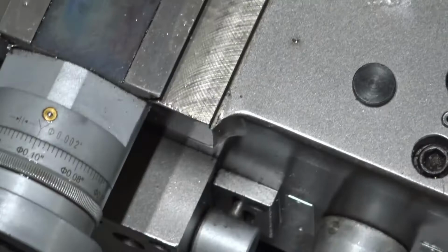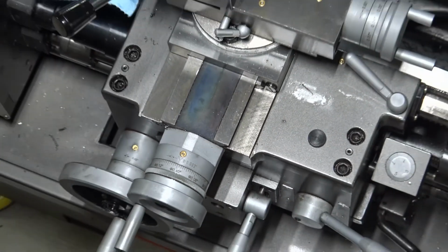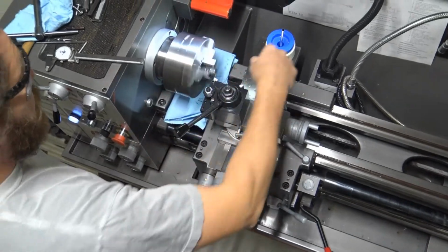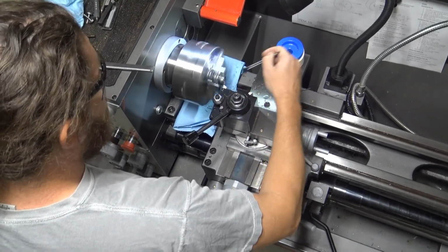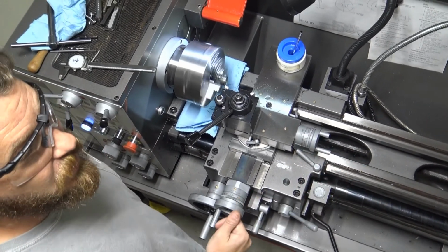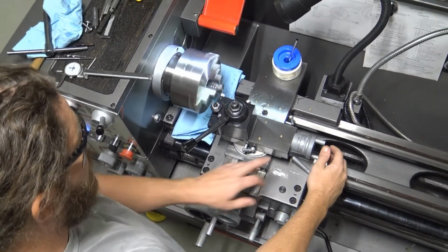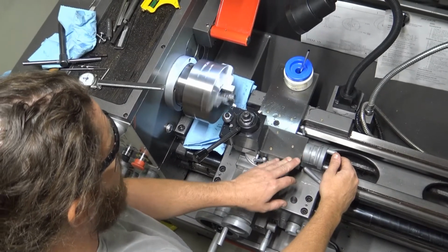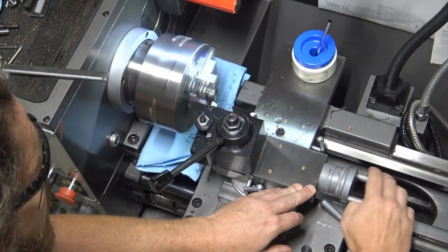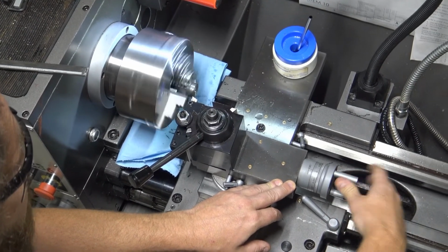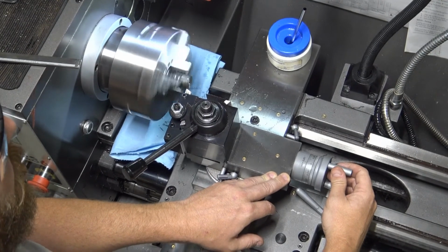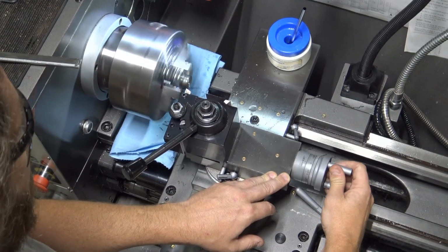All right, I will turn on my machine. Use some cutting oil, and then now I'm going to go into the part 180 thousandths. You should be able to see here on my dial me going in 100 thousandths. Right now I'm just trying to get back to my 0. Right there is the face of the part at 0. Now I'm going to drive it in to 180.